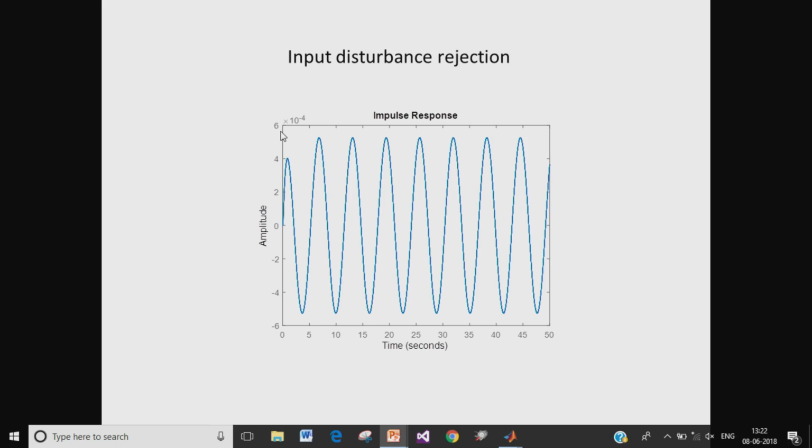So, with this we come to the end of this section on quantitative feedback theory, and the goal of this particular clip was to introduce to you the different functions in the QFT toolbox that you can use to firstly draw the plant templates, subsequently compute the bounds on different performance and stability specifications, plot those bounds, obtain the intersection of these bounds, and finally perform loop shaping and pre-filter shaping and complete the design. The toolbox also allows us to check for performance both in the time and the frequency domains, and even that has been discussed in this clip.